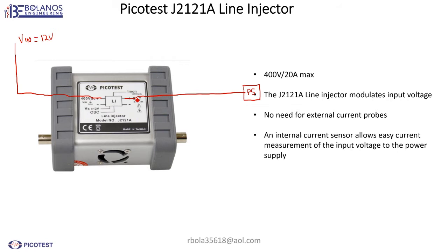Okay, now the 12 volts comes in, and you've got 12 volts coming out, powering your supply, or whatever voltage you set, plus there's going to be an AC signal. Okay, where does this AC signal come from? Well, it comes from this side. If you notice, there's an oscillator there. It comes out through here.